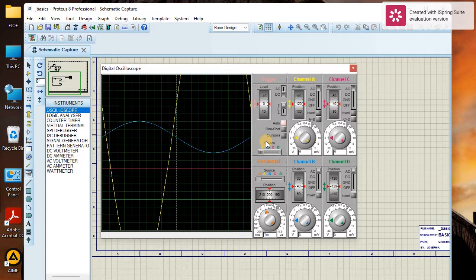Now I can alter these values so that I can visualize the signal inside that window. The visualization window is usually very small, so you can lower this value. What we are actually doing is setting how much each box in the grid is worth, and in so doing we are altering the shape of the signal.